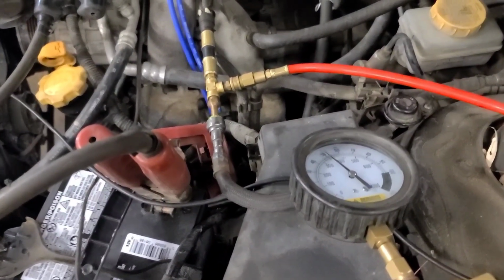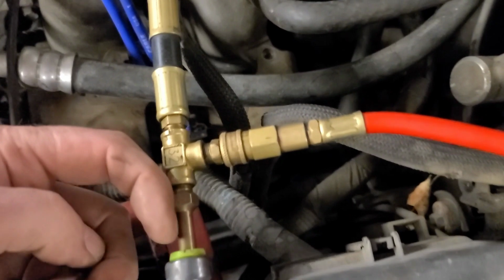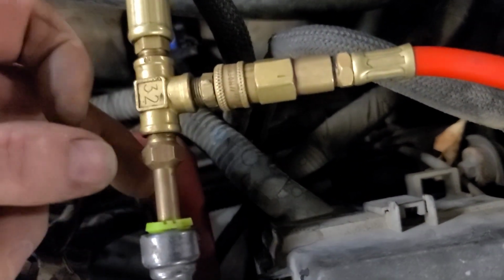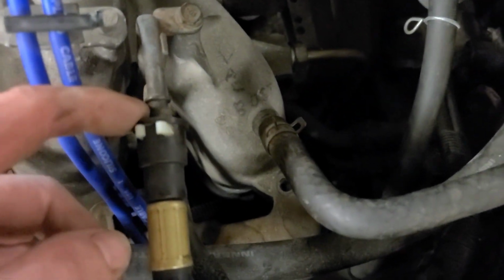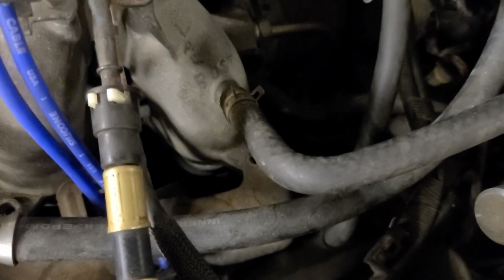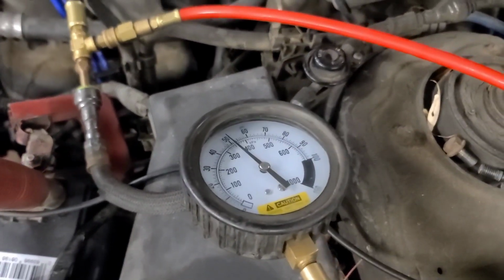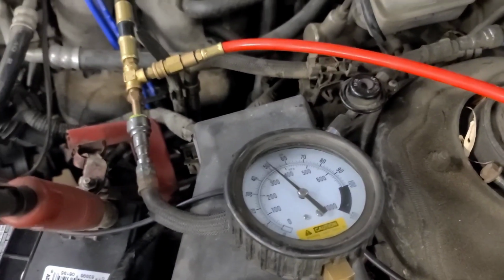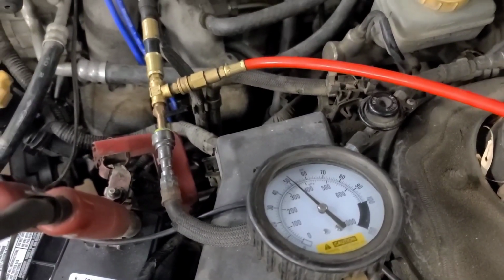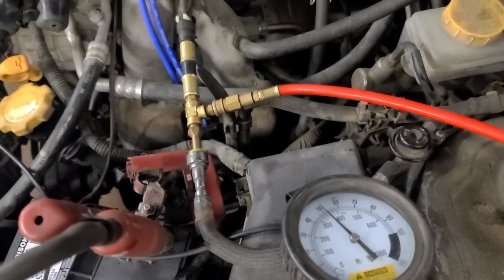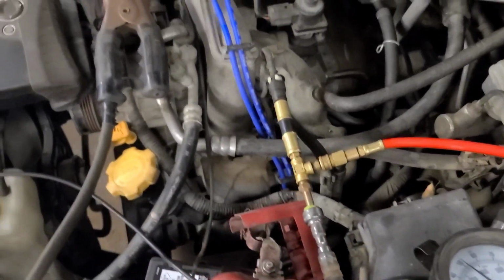So I managed to get that fuel line off. There are two little release tabs that you have to use a 90-degree pick in here to release. Because they put this rib on here, you can't use a normal tool, it's too close. Subaru may have a special release tool, or maybe not. Check fuel pressure, although fuel pressure is not the issue in my opinion. It's got no freaking spark. I mean, I put a spark tester on it now that it runs, and it fires a spark tester, jumps 3/4 of an inch.